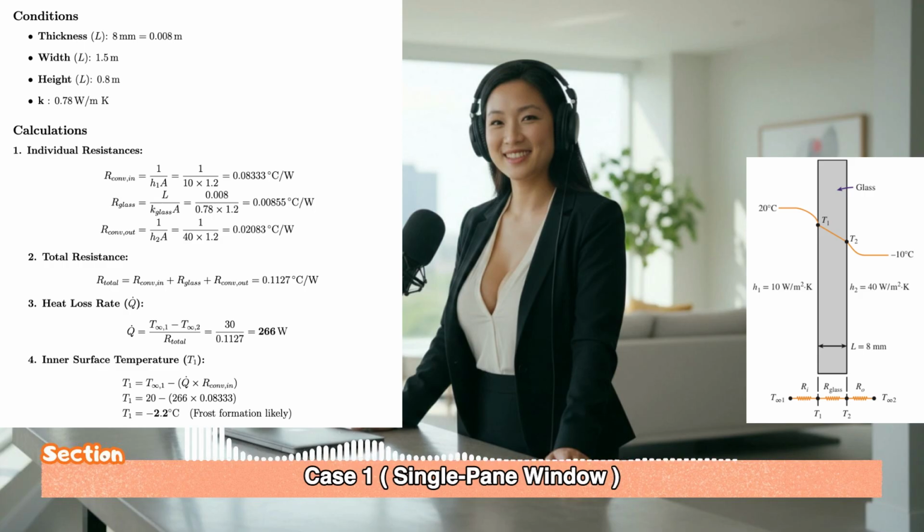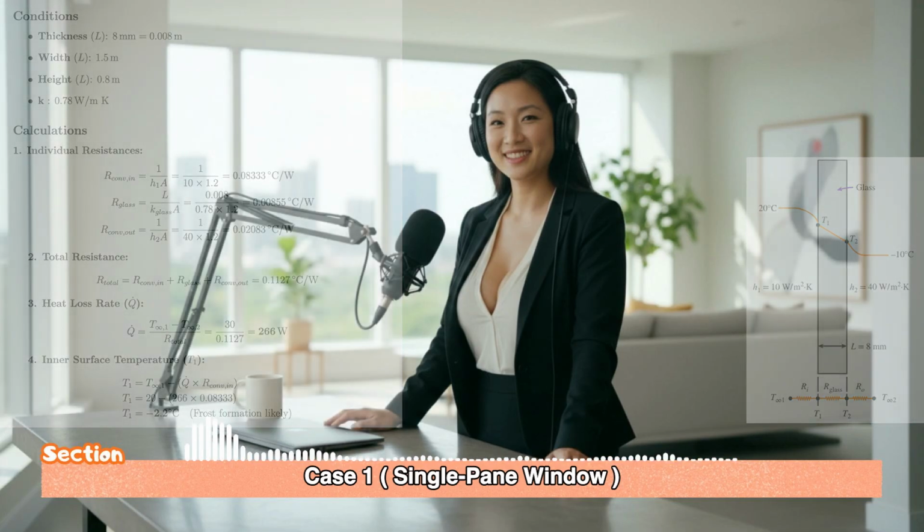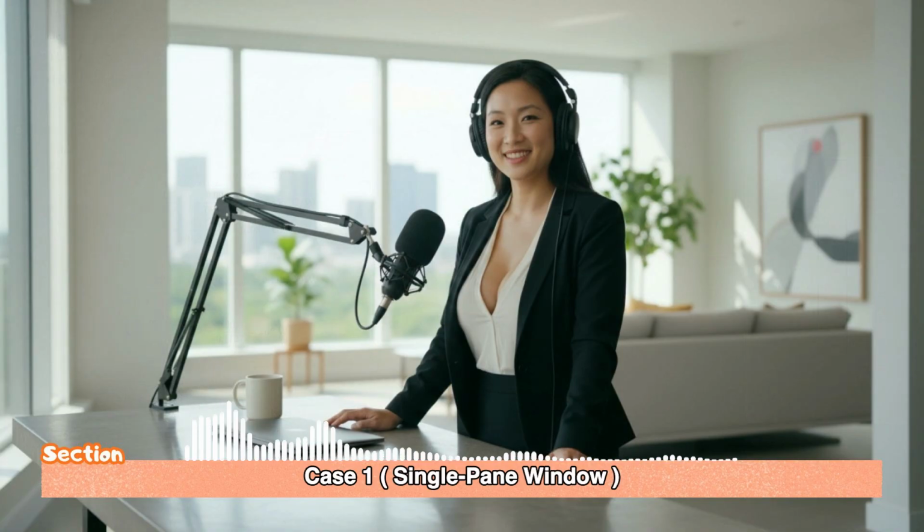We have to calculate the inner surface temperature, T1. T1 equals the inside air temperature minus the heat loss times the inside resistance. So 20 degrees minus 266 times 0.08333, and you get an inner surface temperature of minus 2.2 degrees Celsius. Below freezing. This is why sitting near an old single-pane window in winter feels so miserable. Any moisture in the room hits that surface and just freezes. You get frost. And from a comfort perspective, you are literally a radiator for that window. Your body is radiating its warmth toward a surface that's below freezing. It's a huge source of discomfort.